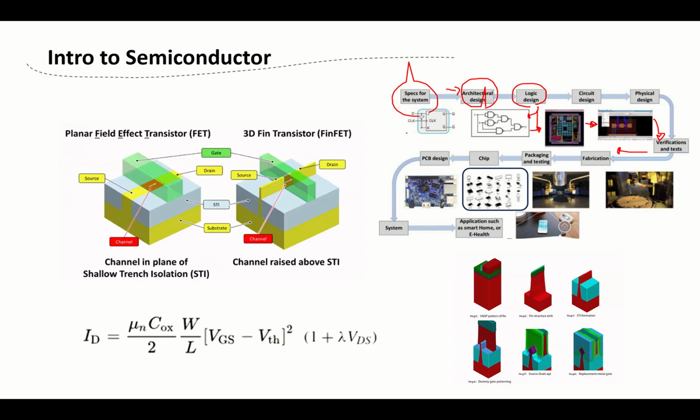From the upstream to the design house, sometimes it will be the same company, like Nvidia, or Tesla. Tesla will have their own needs for chips, so they will design by themselves, or Intel. After that, they send it to fabrication. Based on the GDS file and the layout, we have different masks to fabricate a chip by lithography, by etchings, by diffusions. In here, companies will be like TSMC, Global Foundry, Intel, Micron.